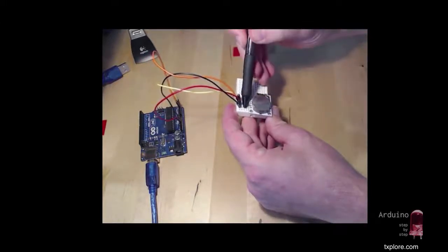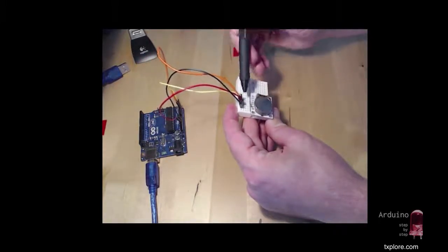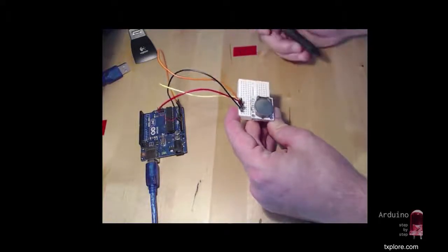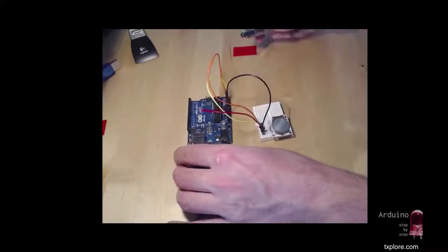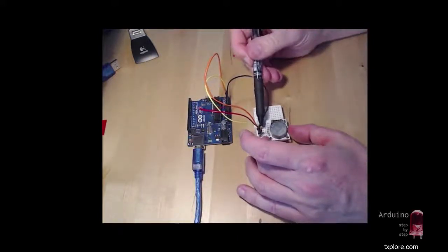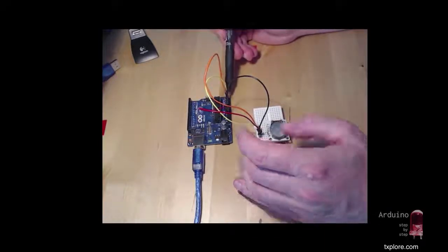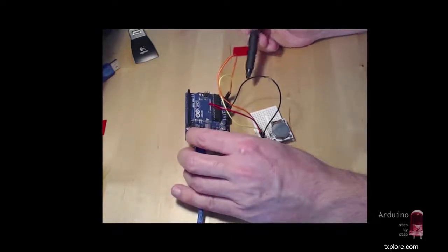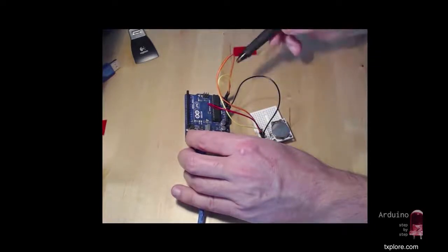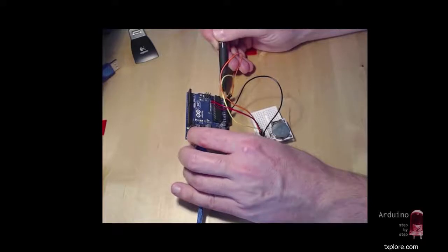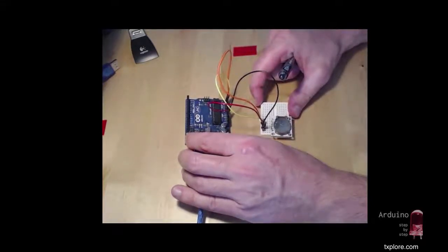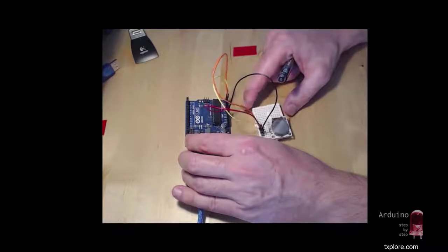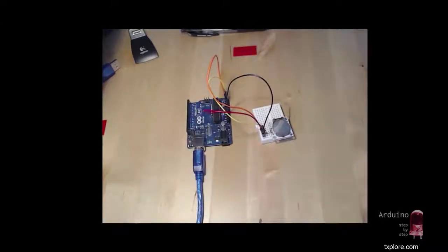I'm being careful so that this row here goes to the ground pin, then I've got 5 volts, then I've got the SDA pin, which is the data wire, and then the serial clock pin is the yellow wire. On the Arduino Uno specifically, the serial clock for the I2C bus goes to analog pin 5. So A5 is marked on my Arduino Uno board. And then the data pin, the orange wire, goes to A4, so analog pin 4. This is specifically for the Arduino Uno. Other boards have other pinouts for the I2C interface. I'm going to show you those in a minute. And power. That's all I need to do for now.